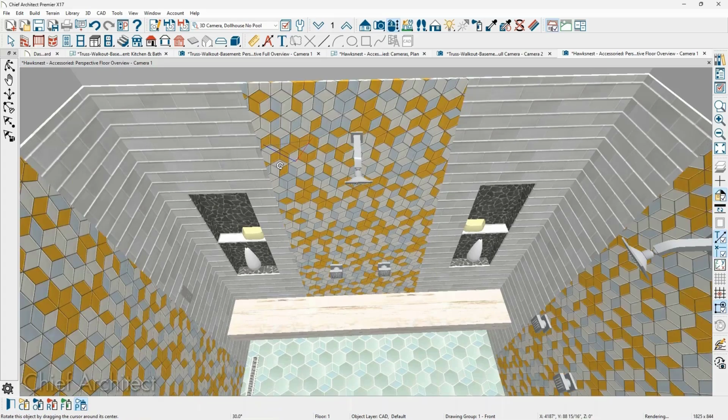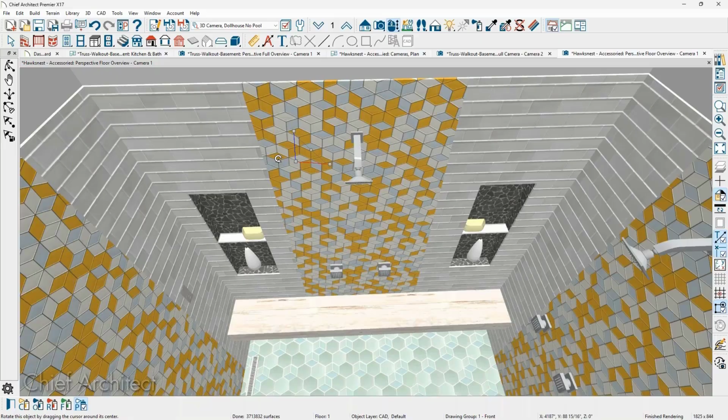And so if you're going to be doing a tile installation program, if we were in a vector view, which is typically used for a tile, you may not see the same effect here because this is restricted to the standard view. But make sure your line drawing is on in the standard view, and then that line drawing should translate and your vector view should look good for a tile installation diagram. So it's a fun new tool. Hopefully it makes it easy so you don't have to go into the material and calculate the X and Y offsets as well as the scaling, and should be very helpful in adjusting materials.